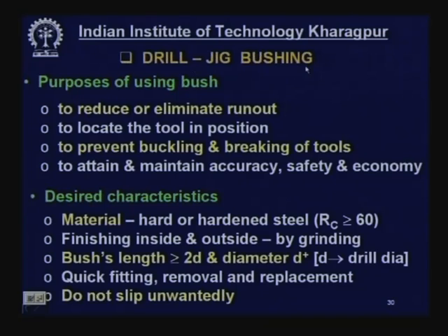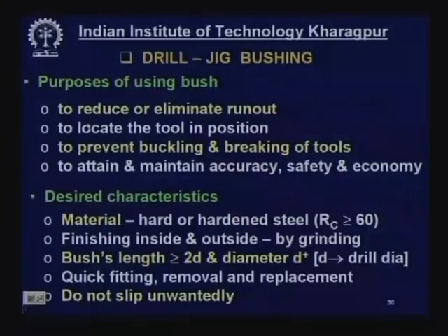Finally, I told you that slender rod-like tools which rotate with a run out lose accuracy, and they may bend, undergo buckling and may break because of the force. Now, for these things the bushes have to be used. What are the purposes of using a bush?